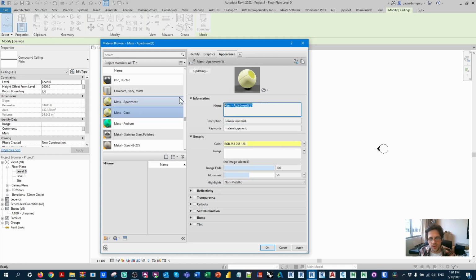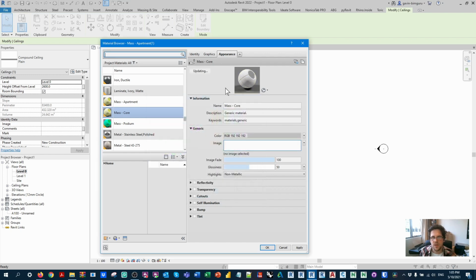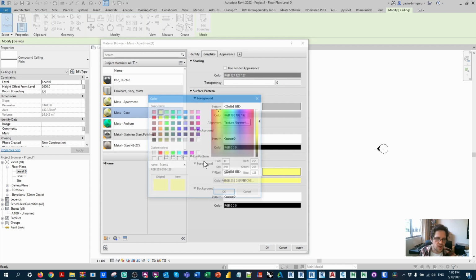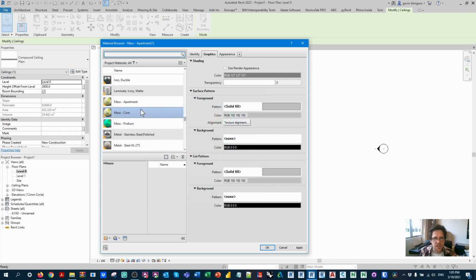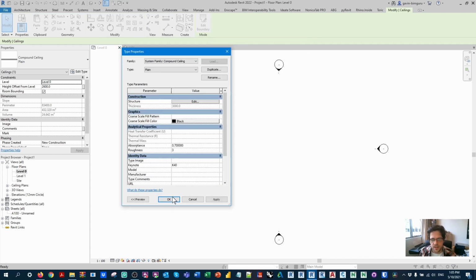So these would be like corridors and cores. And the good thing about using ceilings is that you can use sketch boundaries, so they're much more flexible in terms of how you lay them out. You don't have to lock yourself down to like a box like that filled region, because of course you could make a family like a generic model that behaves very similarly to that detail item box that we made. But at this point I have 3 materials available. This time we don't crash.